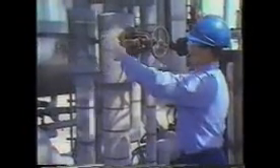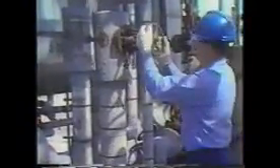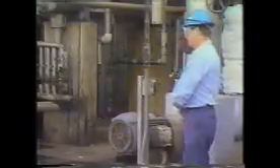Then the outside operator shuts off the steam jets. Jet number 1 first, then jet number 2. When the vacuum system has been shut down, the column can return to atmospheric pressure. Once the column has returned to atmospheric pressure, the outside operator shuts off the recirculating pump at the bottom of the column. By this time, the mixture has cooled enough and further recirculation is not necessary.